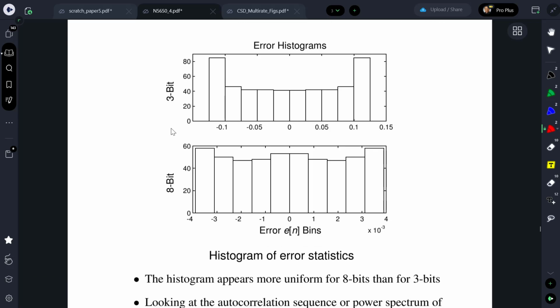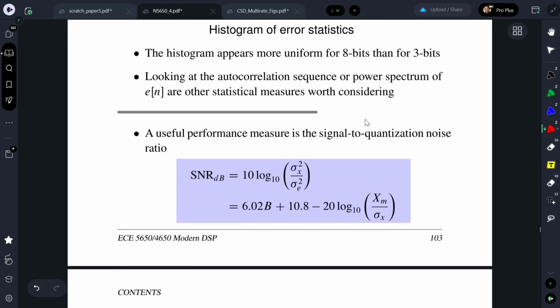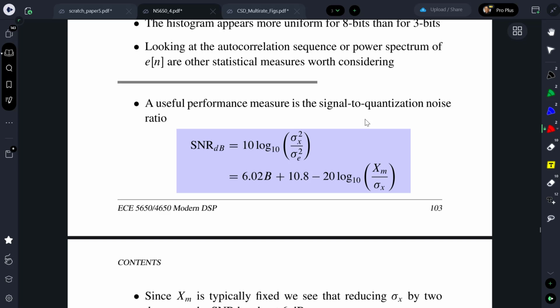It still works fairly well, and I'm going to be able to demonstrate that, perhaps not today, but this is our quick back-of-the-envelope calculation that lets us get the signal to quantization noise power ratio in dB. Variance of the signal power and variance of the noise power is what this is doing. So this calculation here is what you have to calculate for whatever your input happens to be. If it's a sinusoid that's getting quantized, this is just 1/2 A squared that you're familiar with for the power in the sinusoid. And then, of course, sigma e squared is just based on the properties of the quantizer.